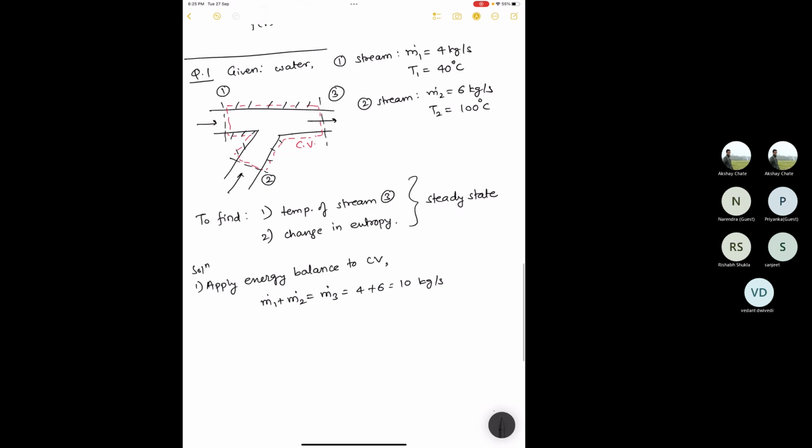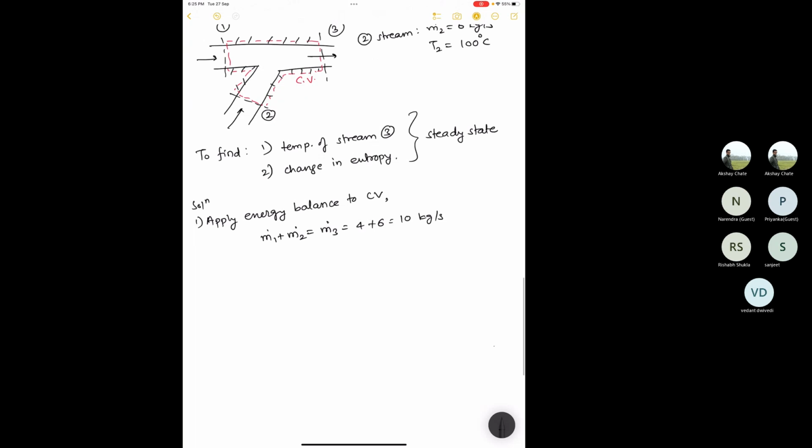Let's make it simpler. If it is not adiabatic, depending on the size of the heat loss, you can take that term in the first law. So this is actually a mass balance. I have written energy balance, so don't get confused, because eventually you have to write the energy balance. The energy balance will be something like m dot 1 h1. You are neglecting kinetic energy and potential energy changes. Whatever I told you, these assumptions also you need to write if you are writing a subjective paper.